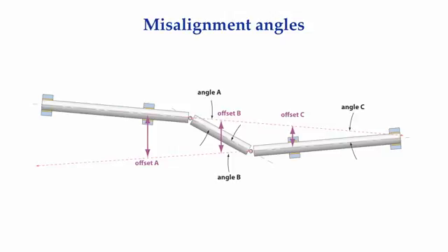Depending on who you talk to, you'll get different answers. For the majority of people I know who have a pretty good understanding of shaft alignment, it's angle C and offset B that they are typically talking about. However, when we usually discuss angles, we talk about angles in degrees of arc. Why, then, is the angular misalignment expressed in mils per inch? Because no alignment measurement system in existence is measuring angles. Everyone is measuring distance. Then we input specific dimensional information on a drive system.